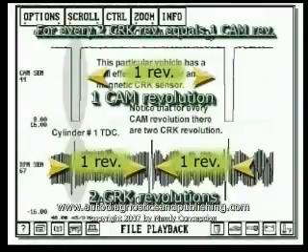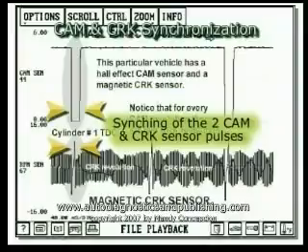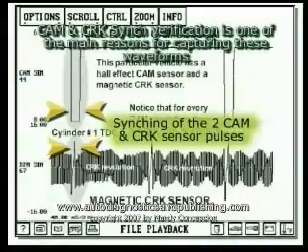It is very common to see an engine that will not start due to a loss of synchronization between the camshaft and crankshaft. The end result will be an ECM cutting pulsation to the injectors in an effort to protect the engine from mechanical damage. It is useful to develop your own signal waveform library for later reference when diagnosing these systems.